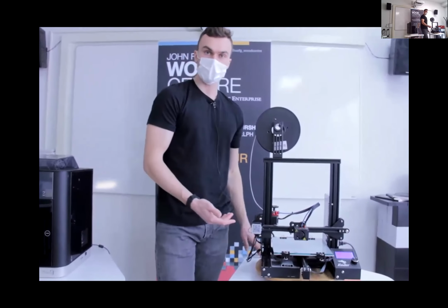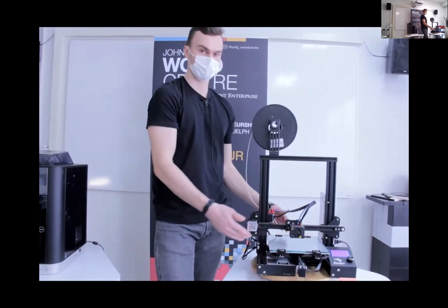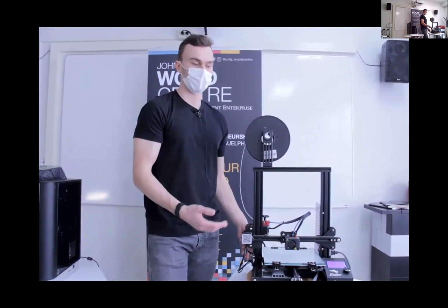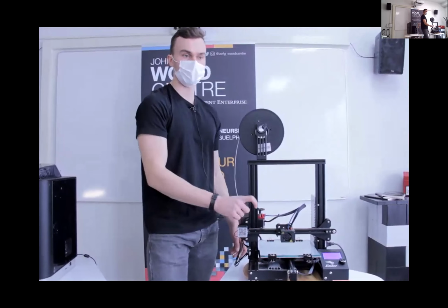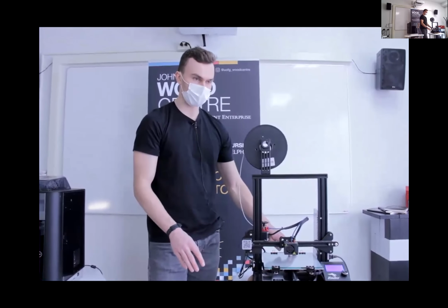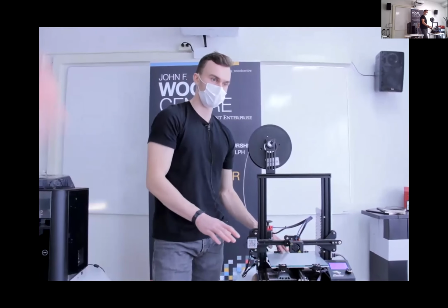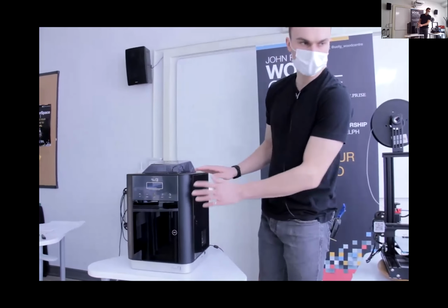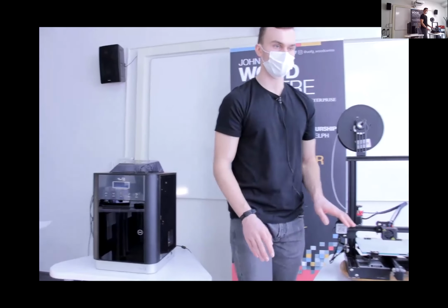to print. So something else you can do to help on an open bed printer like this is use some sort of adhesive that's not permanent. A lot of people like to use a bit of a glue stick on the print bed or a quick spray of hairspray. Whatever you do, make sure it's compatible with your print bed and your printer. The Ender 3 with a glass bed is fine to take that, but with the Cubicon printer, it's all enclosed. We don't have to worry about that. That's only with open bed printers, really.